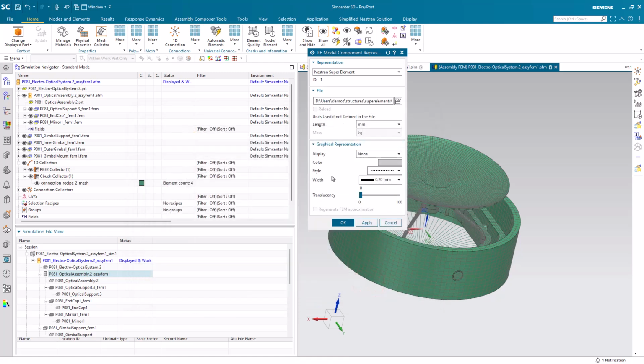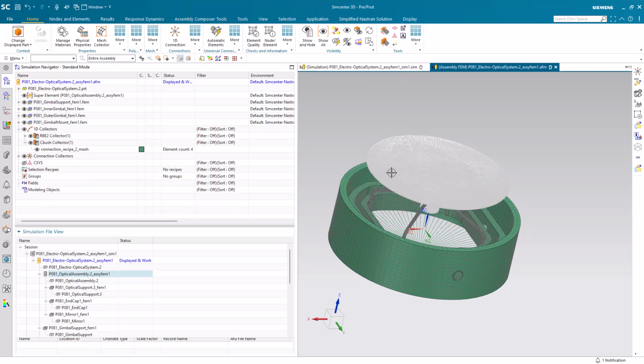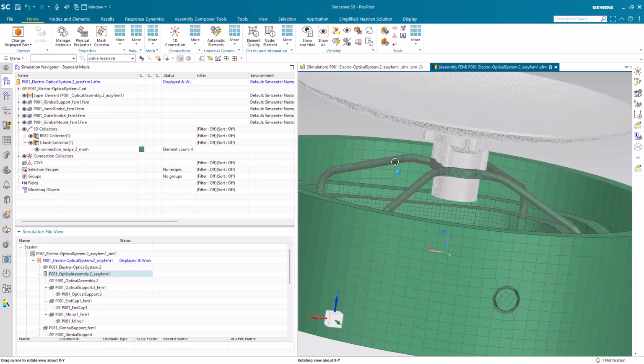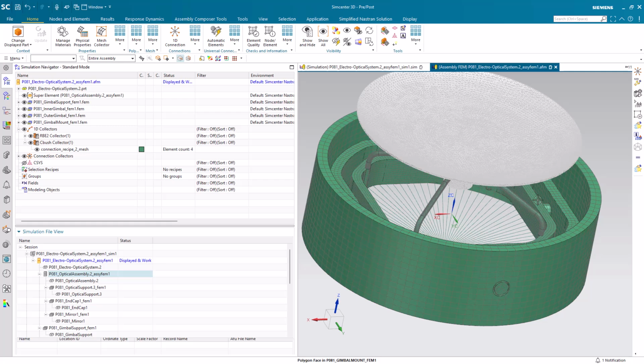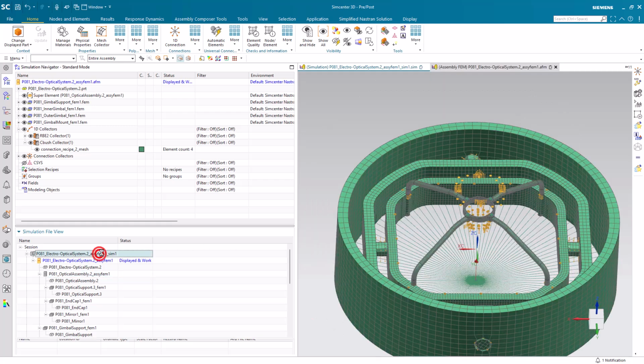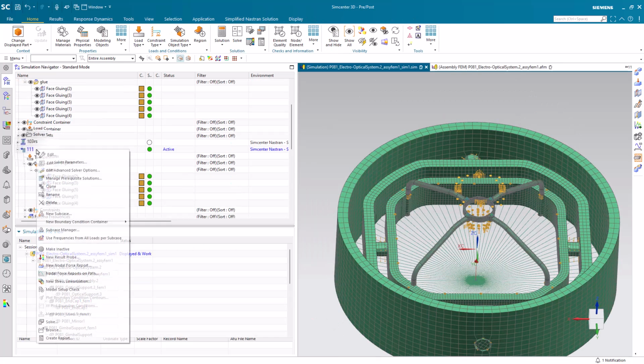The _0 OP2 is the one that we want. That's the DMIG OP2. And we'll select an approximation of the base FEM and regenerate the FEM representation. So now that we've edited the representation of the base FEM to be the superelement, there are only those 4 A set nodes that remain.